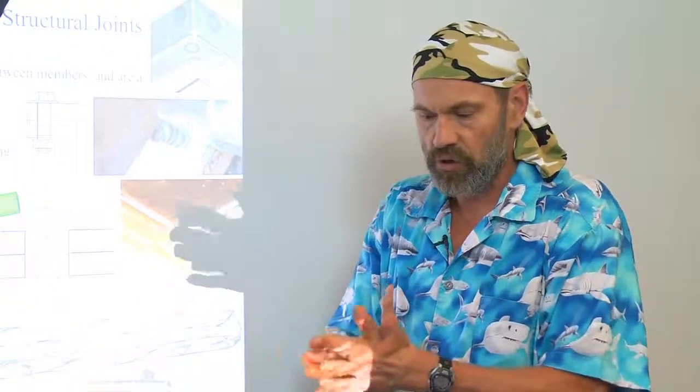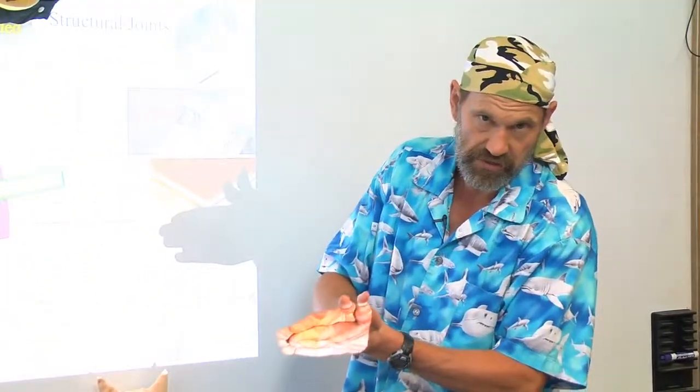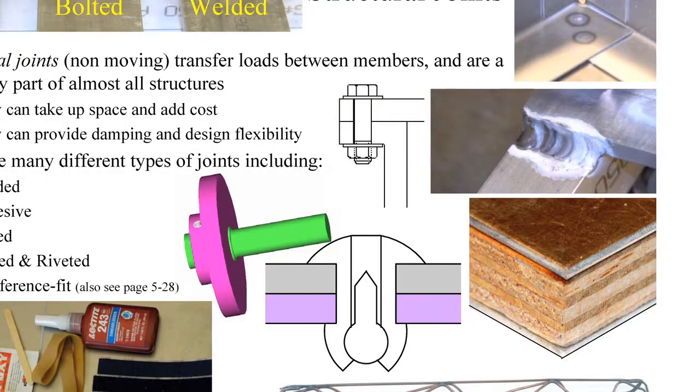The bolted joint holds by squeezing together, and then the joint is held by friction. Whereas remember, the rivet, when it goes in and expands to fill the hole, now can take loads purely in shear. And then welded joints, where of course the metal from the two parts is fused together by heat.